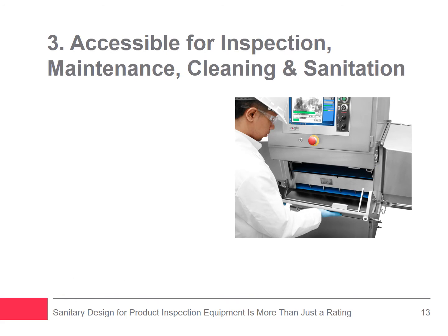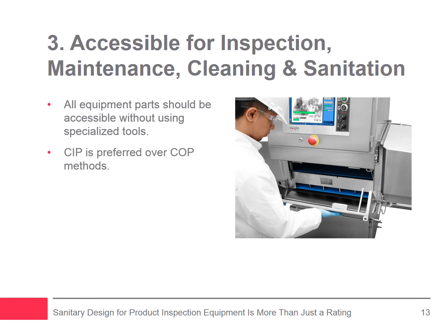Principle 3. Accessible for inspection, maintenance, cleaning, and sanitation. All parts of the product inspection equipment should be readily accessible for inspection, maintenance, cleaning, and sanitation without the use of tools. Clean in place, CIP, is preferred over clean out of place, COP, to avoid time-consuming disassembly and reassembly.